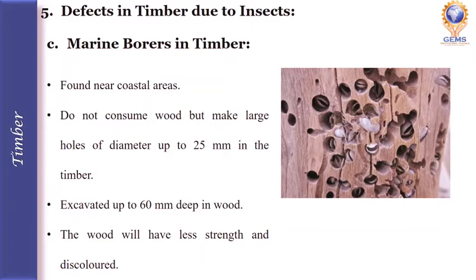Last one is marine borers in timber. Marine borers are found nearer to the coastal areas. These marine borers do not consume any wood, but they make large holes of diameter up to 25 mm in the timber to live inside it. They won't consume any wood, they just want to live inside the wood. They make large holes. They excavate up to 60 mm deep inside the wood.